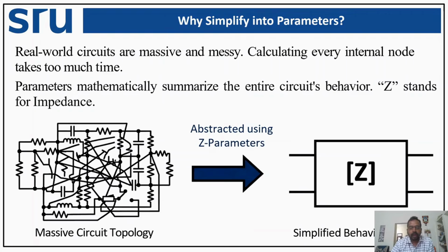Now suppose someone asks you to determine certain performance quantities of this particular complex interconnection. So what do you do? For example, they may ask you to find the input impedance seen from the source. They may ask you to determine the voltage gain between two points. They may even ask you to compute the current response under certain loading conditions. Each time such a question is asked, what would you like to do? You need to solve this circuit from scratch. That is, you need to apply mesh analysis or nodal analysis or any other circuit reduction technique.